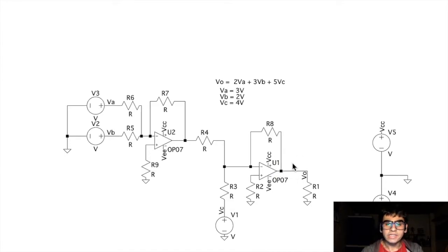Now, to get the result, which is the answer of the linear equation, on this schematic itself, we'll also need to place an output label which is used for DC bias point analysis. Go towards the output terminal of the whole circuit and right click on the wire. We can see the Place .OP Data Label option, so select that option and you'll get question marks here. These question marks will be replaced by the actual value of VO when we run the schematic. Now finally we can set the values of all the components.